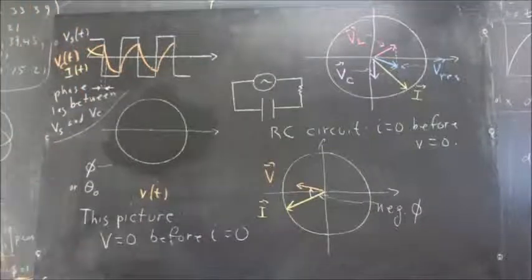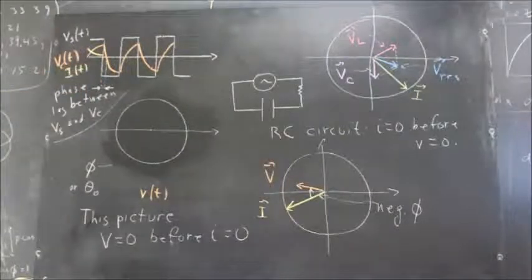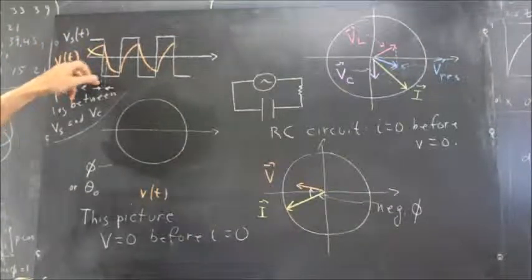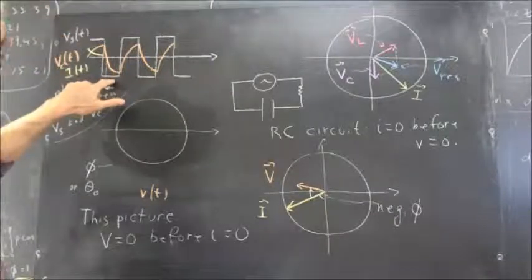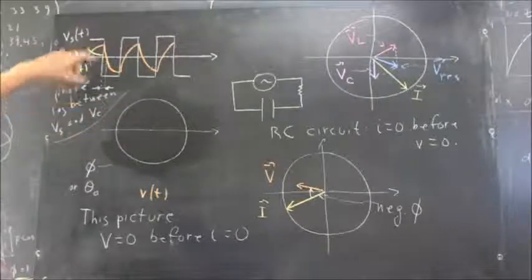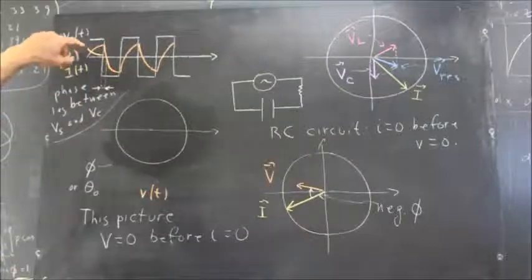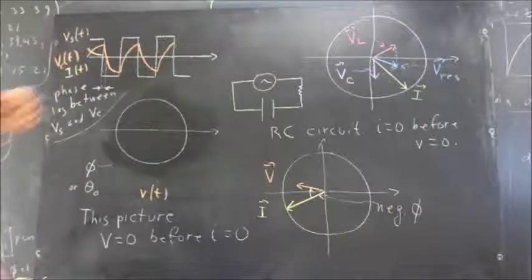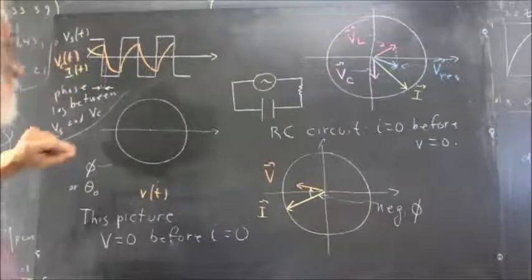Okay, the current curve. Now, what happens when the source voltage reverses? Well, the capacitor is already pushing in the direction of this reversed voltage, so you have the voltage of the source now reinforcing the voltage of the capacitor. They're working together, and you're going to pretty much instantly get a sharp drop in the current.